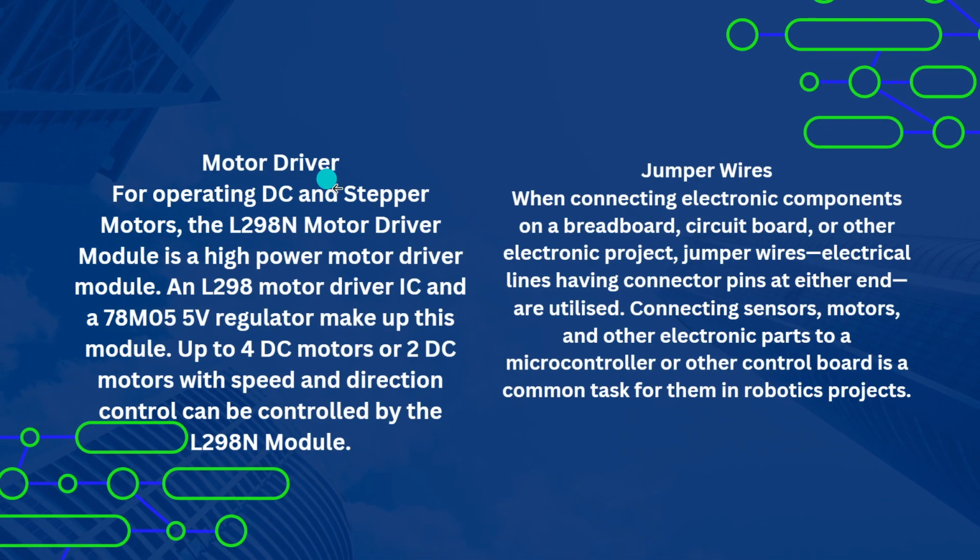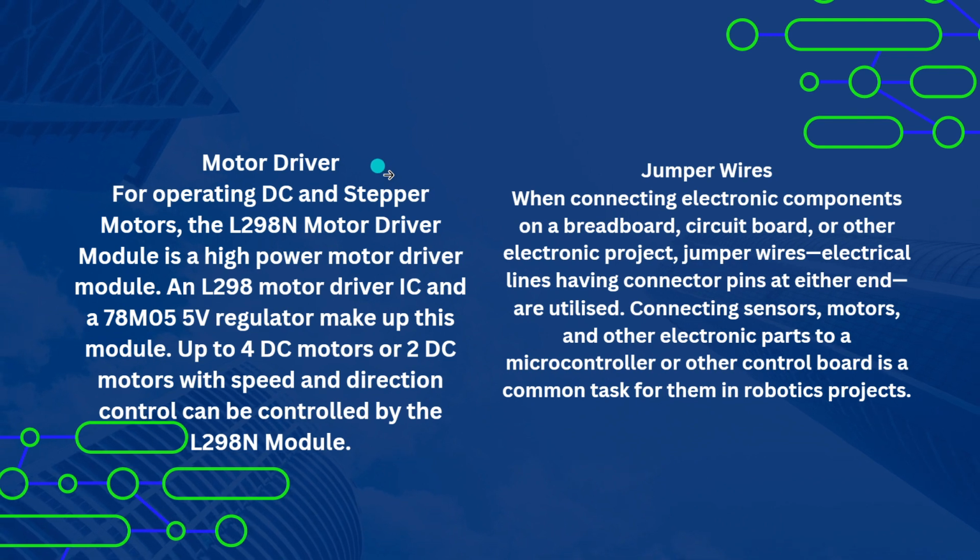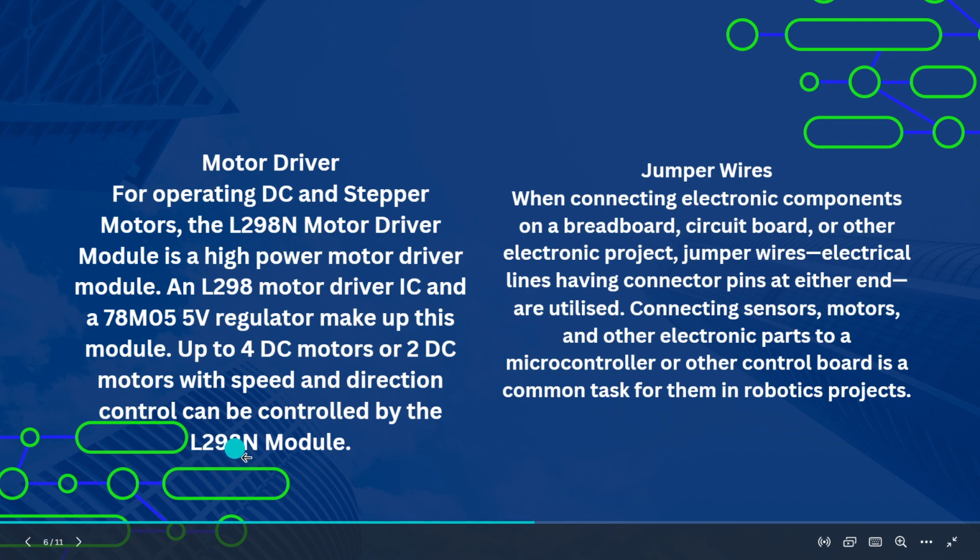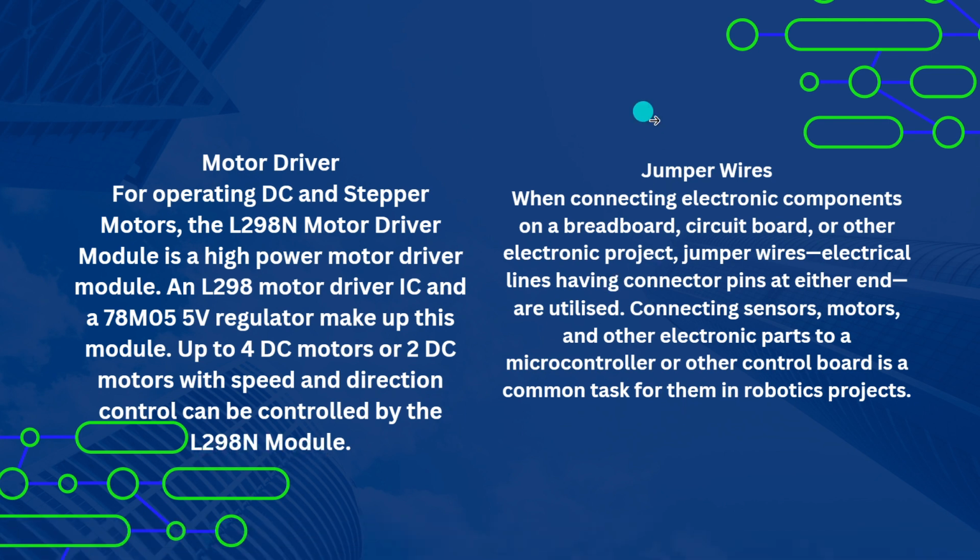Then the motor driver for operating DC and stepper motors. This motor driver, this is the name. It is a high power motor driver module, and up to 4 DC motors or 2 DC motors with speed and direction control can be controlled by the L298N module.